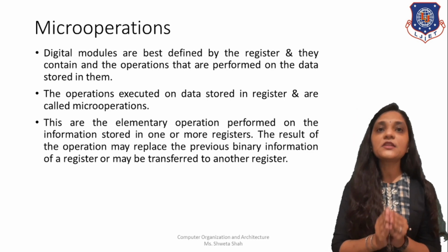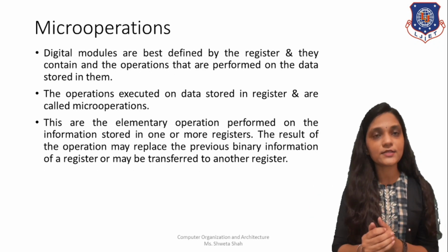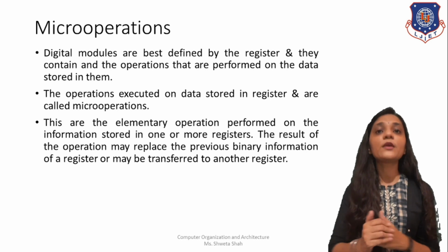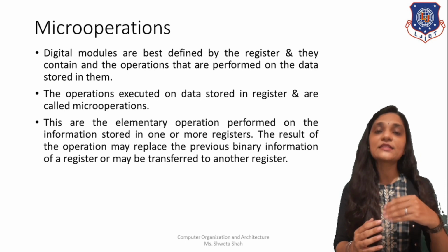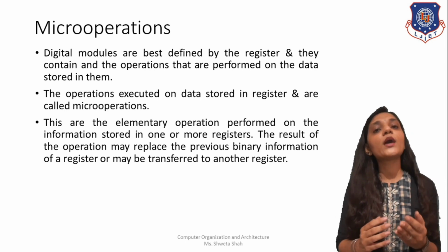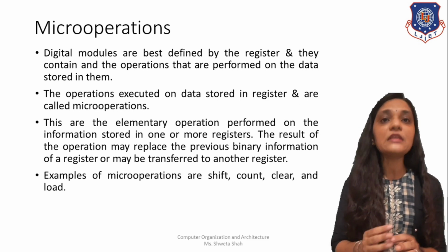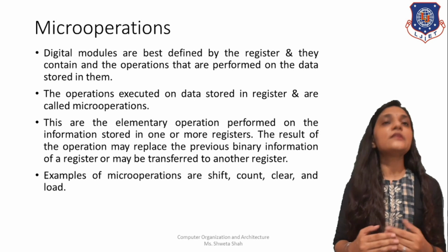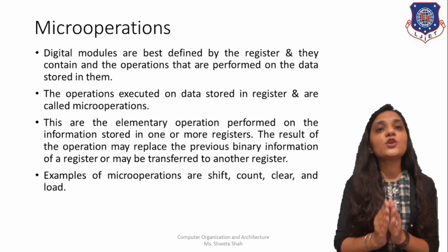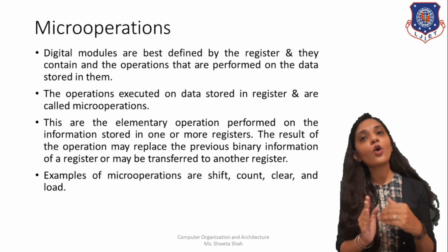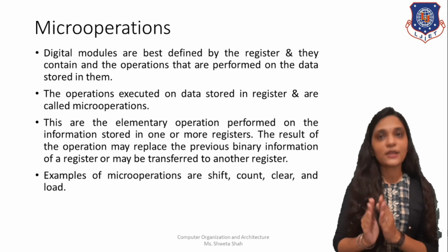These are elementary operations performed on the information that you have stored in a register, and the result of this operation may be replaced into the previous binary information, or you can say in the same register, or if required then it can be transferred into another register. And this operation can be shifting, counting, clearing, loading some content into a register. Okay, so this will be a basic operation that you are going to perform on the content of this register, and that is known as a microoperation.